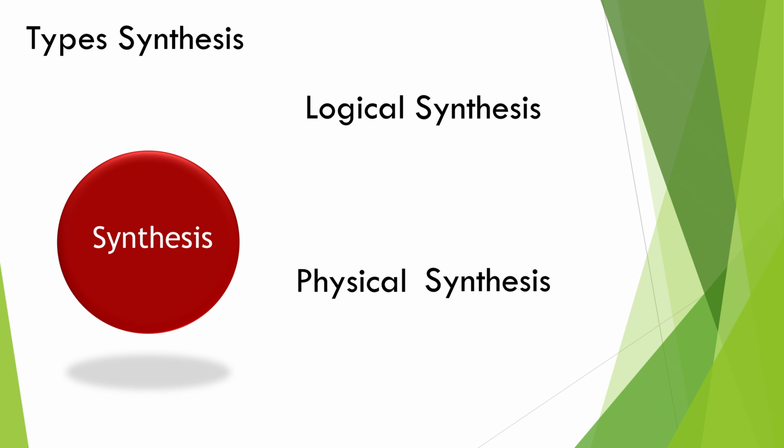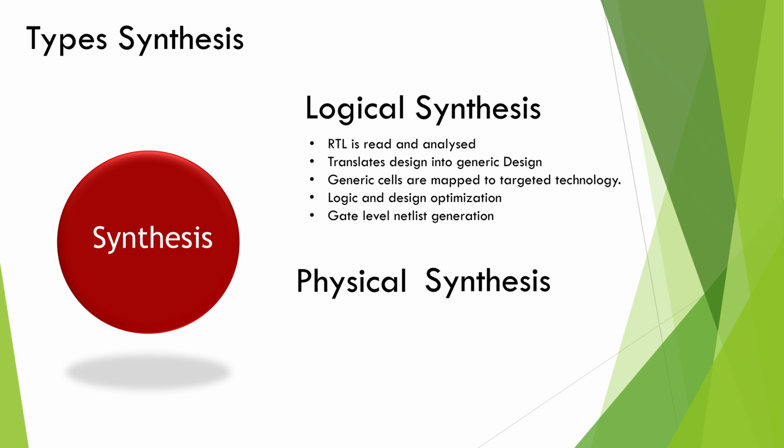Okay, what exactly is logical synthesis? In logical synthesis, the tool reads your RTL, analyzes it, optimizes the logic, and maps it into generic design elements and then standard cell gates, mostly using abstract timing information. So it understands my code at a logical level and decides how to implement the functions, but it doesn't fully know where things will sit on the chip. Exactly. It cares about correctness and timing based on models, but it doesn't yet see the real physical distances between